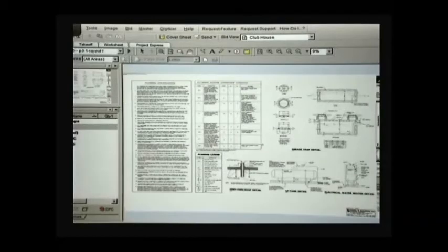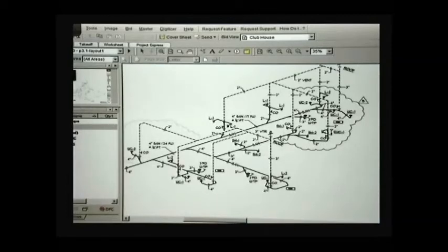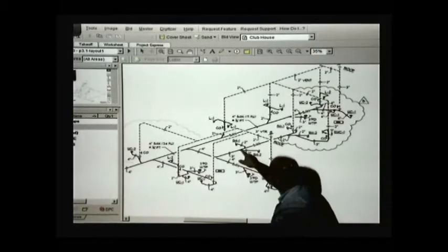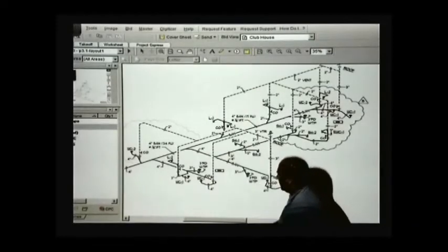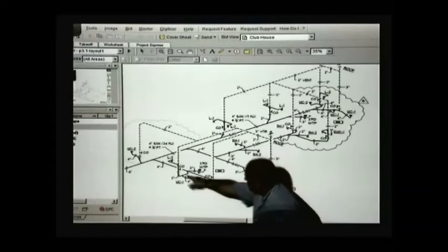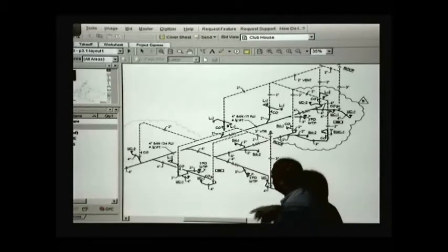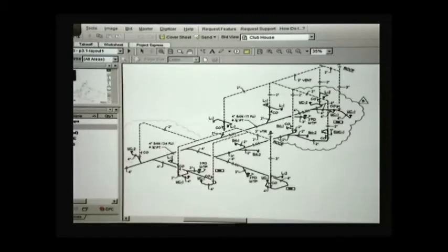Oh, what I was going to say before, if you are by any chance really having to develop a quote for this, or have to do an installation, then you will get into a lot more details. You will have to estimate the number of fixtures that you have. Like, for example, here will be a Y, so it's a piece of pipe that has a connection on the side and it merges two lines. You will have to have elbows on these points where you go either up or side or change of directions. You need an elbow over there. You will have a valve at each one of the points of use, so you can close the pressurized line and do maintenance on the unit if you need to.